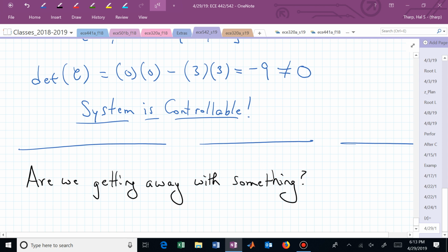The answer to that first question is, where were the closed loop poles in units 6 and 7, or units less than unit 8? Where were our closed loop poles in the complex Z-plane? If we stabilized the system, they would be inside the unit circle, wouldn't they? And were they arbitrarily located inside the unit circle? Well, you're going, I don't remember. Well, pull out a napkin.